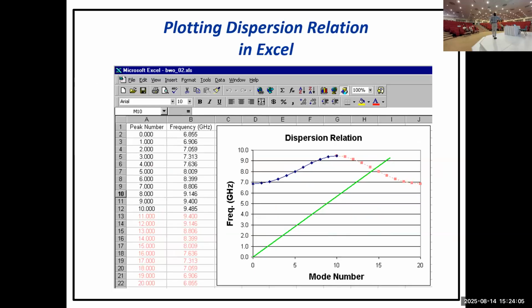But the problem is not that easy, because once you have resonances, you have to go to each single resonance, run your eigenmode solver, and check the mode pattern. That's why I have a slide here showing the circular waveguide mode pattern. You need to look at the mode pattern and make sure it belongs to the passband you are working on. So this task is really not easy.